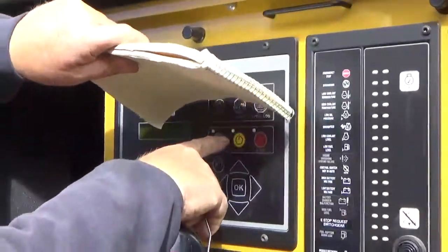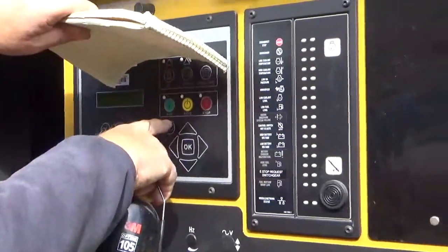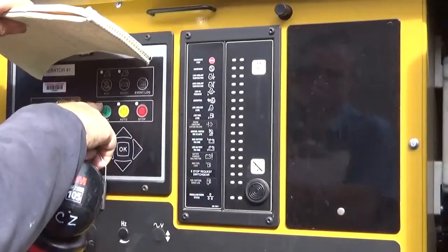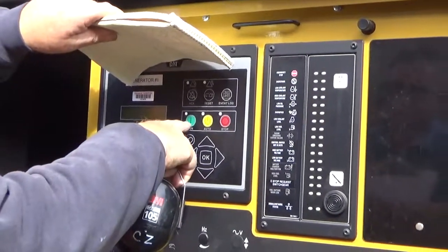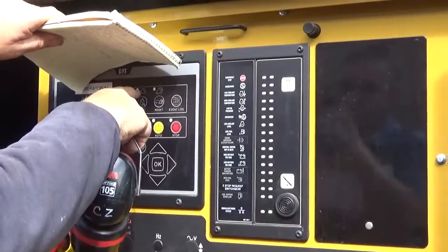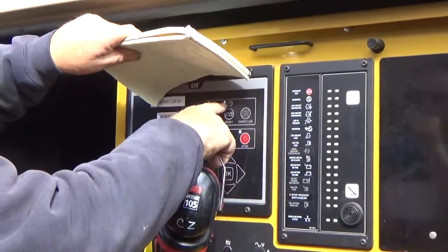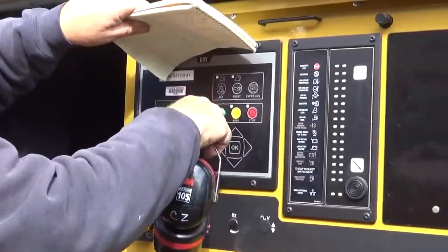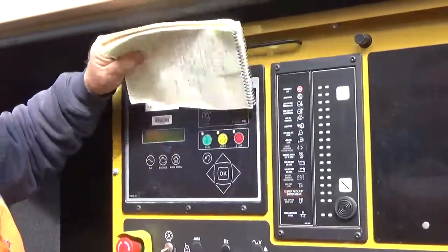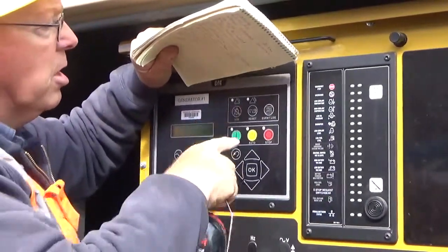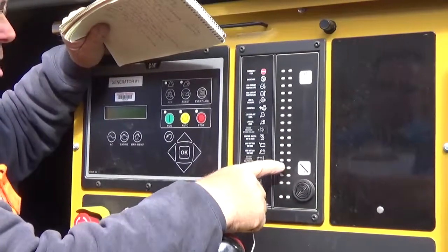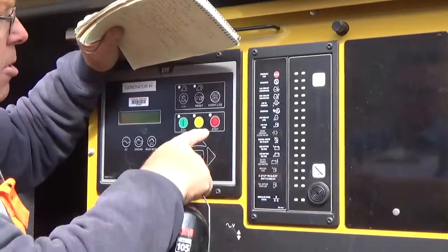So normally your auto position's on and you have a green light above the auto. If you go to run, that light goes out. You'll get a not in auto light, and the light will come on here to run it locally. And this light is any alarm function. This yellow light will blink. Shutdown, this one blinks, this one's red. So if you ever come up to it and the lights are blinking, you have to acknowledge it first. If you hit acknowledge here, it will most likely acknowledge over here if the global annunciation is turned on, which I can tell you right now.